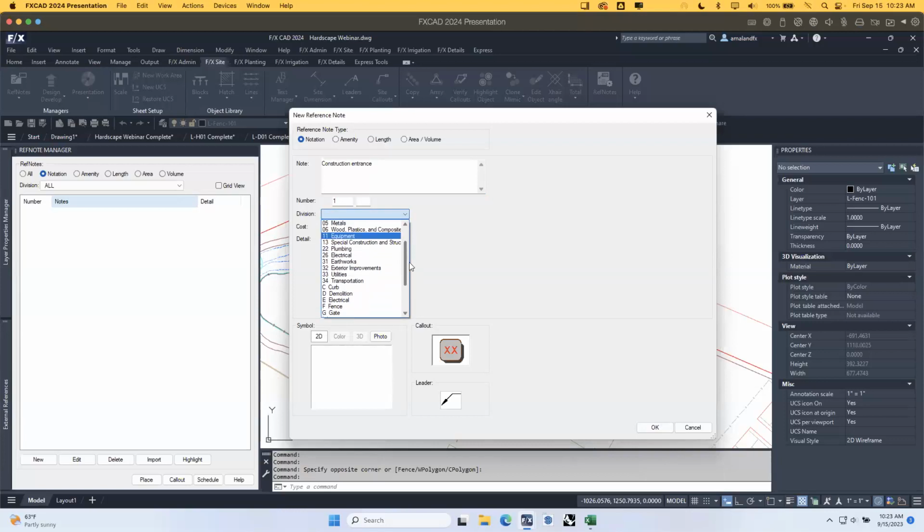So I like using CSI divisions, honestly, because I think that there's a lot more divisions off the bat. It's more standardized. It can easily connect with details and specifications and other disciplines like architecture and engineering. Whereas the letter divisions can sometimes be a lot easier to understand at a glance, because obviously P for paving, S for site furnishing, right? Instead of number divisions. It does rely on the language that you're using though. So if you're in a multi-language environment, CSI is much better.